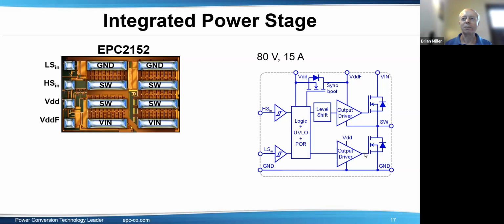So no further protection. I think the questioner might be asking about possibly negative voltage or a diode or different clamps, but no, that isn't used in any design I'm aware of with the EPC GaN FETs.